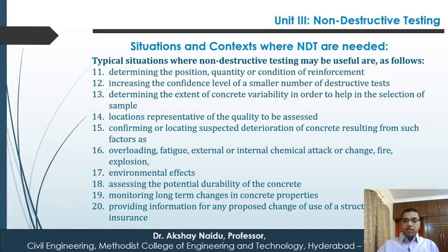Confirming or locating suspected deterioration of concrete resulting from such factors as overloading, fatigue, external or internal chemical attack or change, fire explosion, environmental effects. Then assessing the potential durability of concrete, monitoring long-term changes in concrete property, and providing information for any proposed change of use of a structure for insurance.